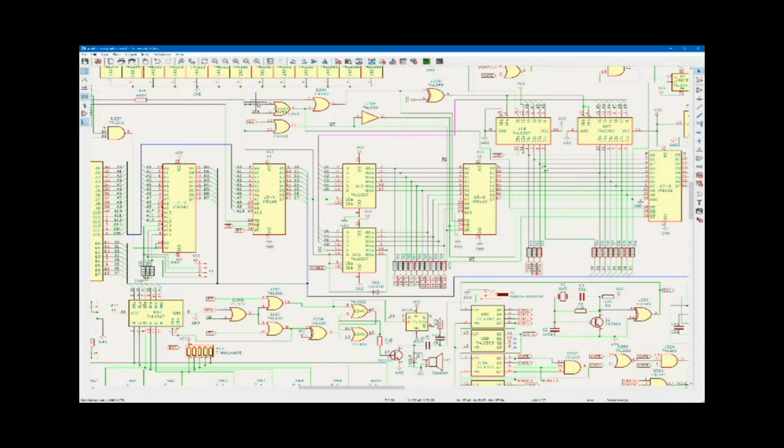About 20 nanoseconds later, a pulse comes out of this gate, and about another 20 nanoseconds later, a pulse comes out of this gate. Then about 20 more nanoseconds later, this one lets the address lines through. That means this write is getting triggered 60 nanoseconds before the address bits are set out here on the address lines. Maybe for some RAM chips, that's all right.